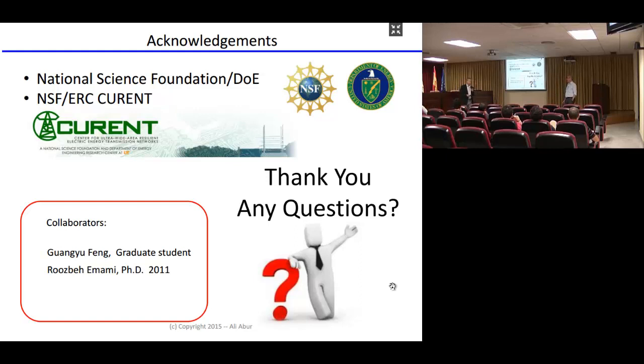Yeah, I'm aware of a couple of papers by these guys from Illinois, Overbye. The first one dealt with single line outages, they were pioneers in this idea, but there's another one, probably a conference paper, dealing with double line outages. And they were using the active power phase angle DC power flow model. So have you tried also double line outages? And another question is, what is the main difference between your work and theirs? I think their work is more of a matching of the signatures, and they don't use this sparse estimation. Whereas here, this is strictly sparse estimation. You put it in the optimization problem, it gives you the solution. I think Yanaki has another contribution in this regard, right?